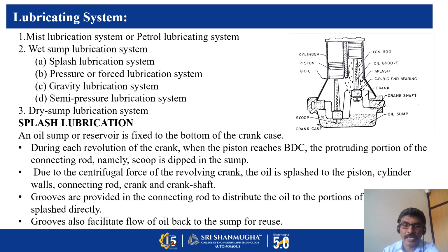See in this diagram, this is the splash, this is a scoop. The scoop will take oil from the sump and, due to the rotation of the crankshaft, it will splash the oil. So here the oil is splashed over the moving parts. Like this, the scoop will take oil from the sump and it will be splashed over the moving parts for lubrication.